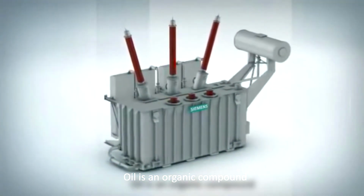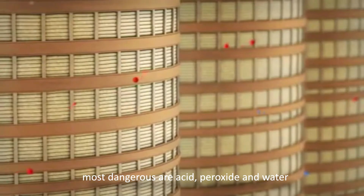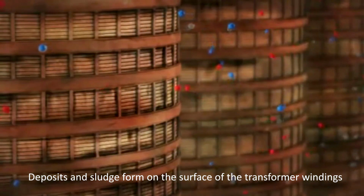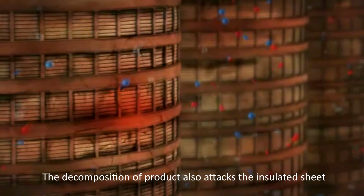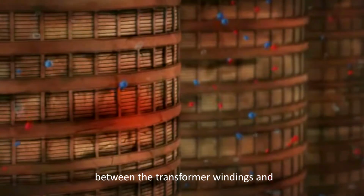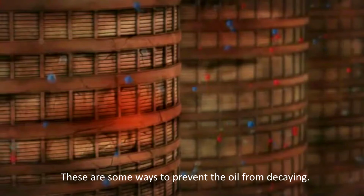Oil is an organic compound. It produces various degradation products. Most dangerous are acid, peroxide, and water. Deposits and sludge form on the surface of the transformer winding. These reduce the heat transfer capability and also the cooling capability of the oil. Decomposition products also attack the insulating sheet between the transformer windings, and the insulating sheet will lose its dielectric properties. These are some ways to prevent the oil from decaying.